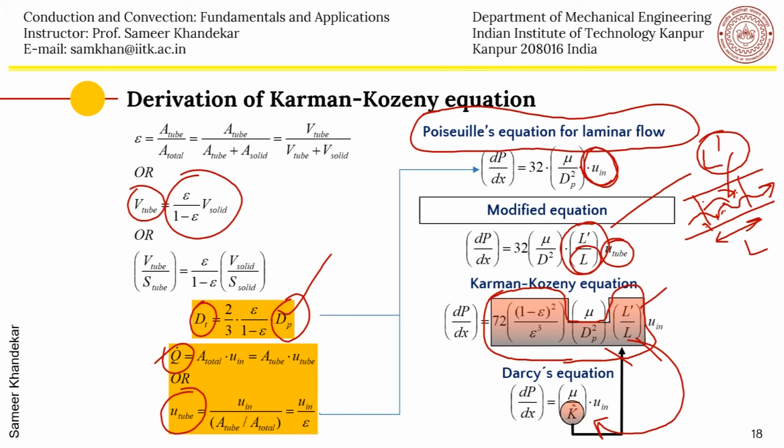The permeability has to be experimentally calculated. So applying the simplest capillary limit, on the left hand side you have the capillary pressure drop, and the gravitational pressure drop, this is the plus. On the right hand side you have the delta P liquid, which is coming from Darcy's equation, and the delta P vapor, either laminar or turbulent.